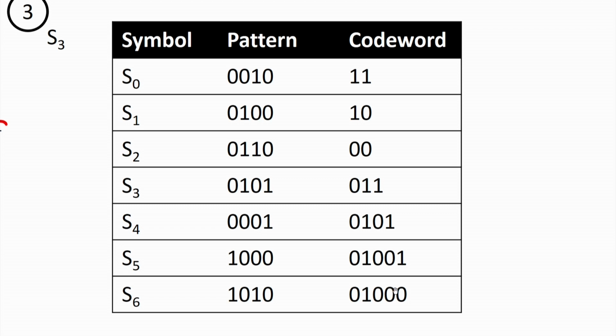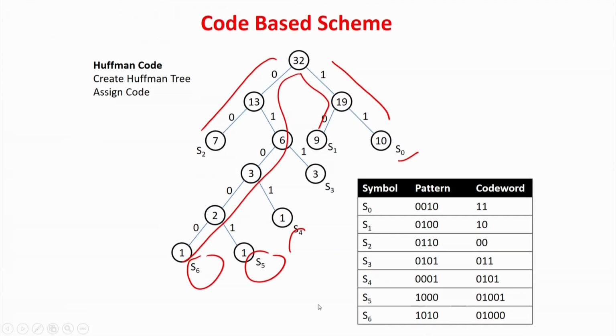The channels are basically also multiplexed. You can multiplex the channels so that you can have more efficiency of the ATE equipment. Depending on requirement, patterns will be sent to your chip, and the same lines will send to the other chip for the other vendor, but they will be multiplexed. So you can see that if we have more number of patterns and you are using all of this, everywhere you will be multiplying by 4. But here these occur more number of times, so only 2 pins are required. That way we basically optimize.